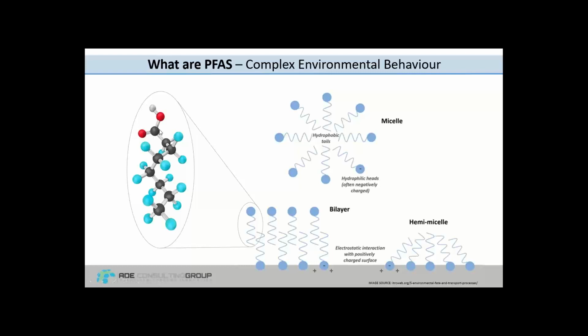If I speak about functional head, I'm referring to the functional group. Typically these are carboxylic acids and sulfonates, but there's a grand number of other PFAS out there, and we'll touch on that shortly. But these are kind of the flagship groups that have been studied. Everyone's familiar with PFOS, PFOA, PFHxS, and to a lesser extent, PFHxA, PFBS, and PFBA, which are the short chain congeners. These are short names that we apply to them, and the name generally refers to how long is the chain and what functional group is included.